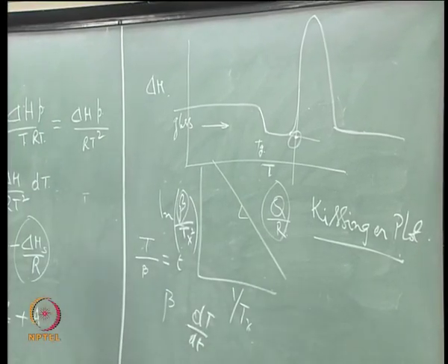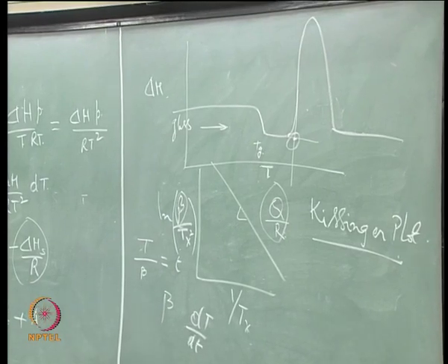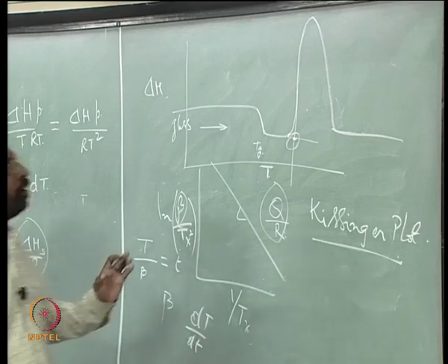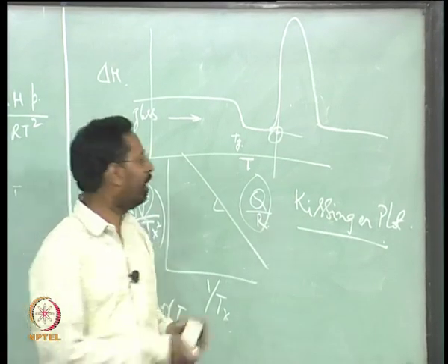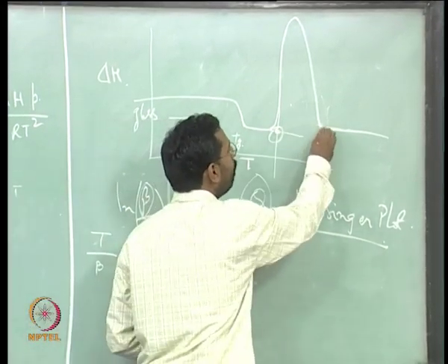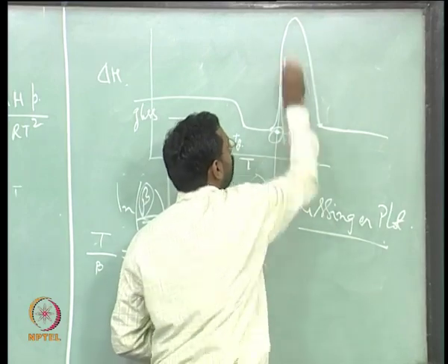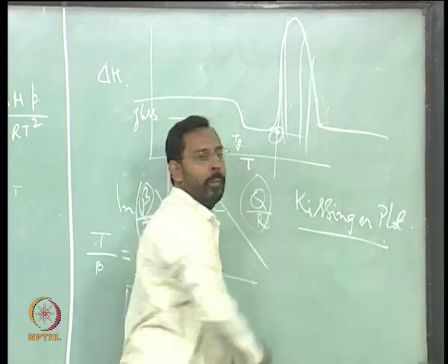So, in principle, if I know the heating rate, the temperature axis can be converted to a time axis. Hold it at a given temperature and, as a function of time, you see how the phase is evolving, and in this process you can talk about how much percentage of transformation has taken place. So, here it is onset, here it is complete, and at any given time here you can talk about percentage transformation.